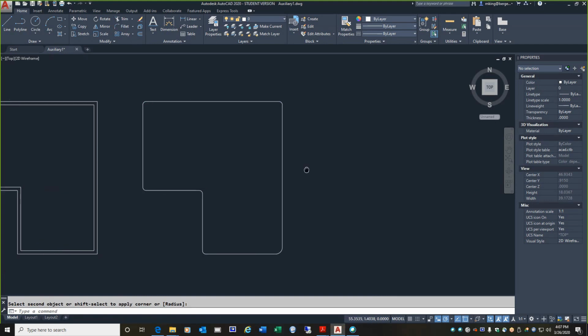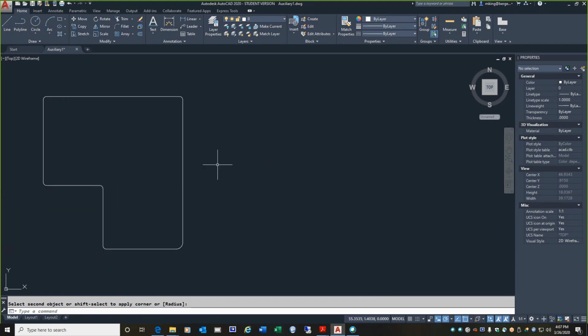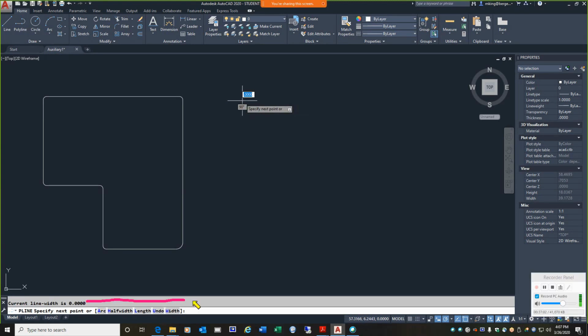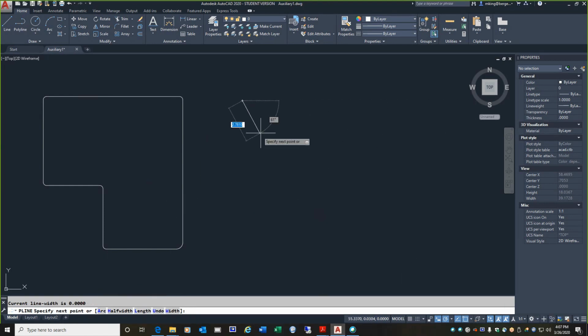All right, I'm going to pan off to the right, and let's see some other good features with polyline. So go ahead and click polyline to start a new one. On your screen, click to begin. Now notice, I want you to start noticing all the different features that polyline has in the command prompt that line does not have. Okay? I'm going to move my mouse over to the right, and this time I'm going to say 6 for 6 inches, 6 enter.